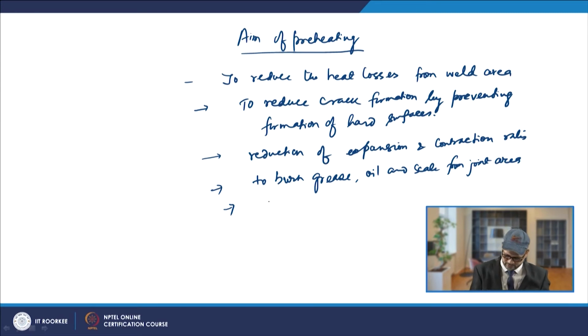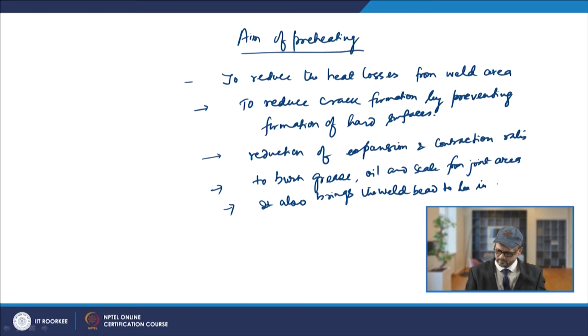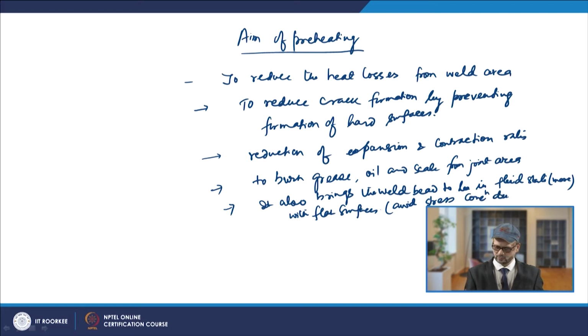So preheating also brings the weld bead to be in a more fluid state, with flat surfaces, and that will avoid stress concentration due to the notch effect.